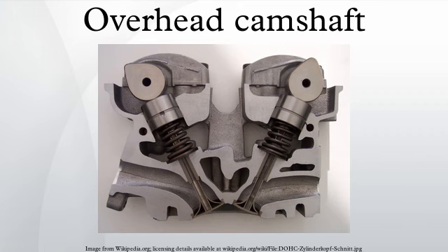Low-priced American manufacturer Crosley used a small, 44-cubic-inch 4-cylinder SOHC engine following World War II. This unusual engine was developed during the war by Lloyd Taylor, licensed by Crosley, and used to power generators and other military applications. The overhead camshaft was driven by a tower shaft and gears. The original design was made of steel stampings, copper brazed together to form a strong and light block assembly. It was known as the Cobra engine and generated 26.5 horsepower in automotive form.